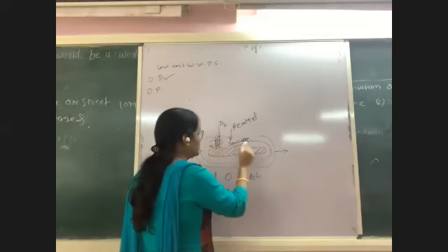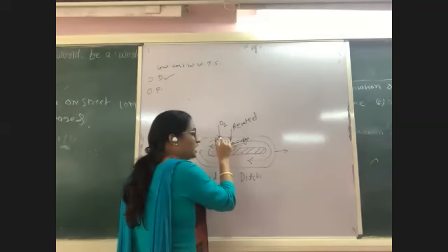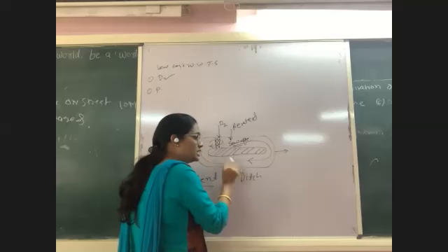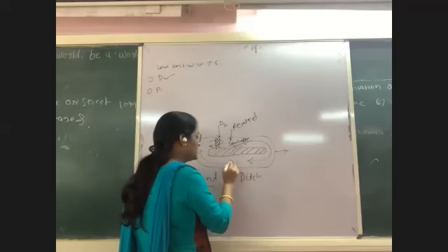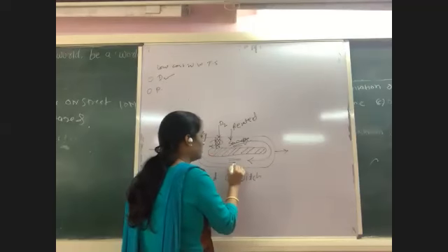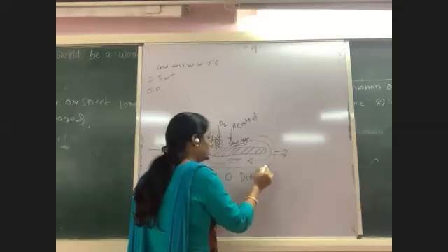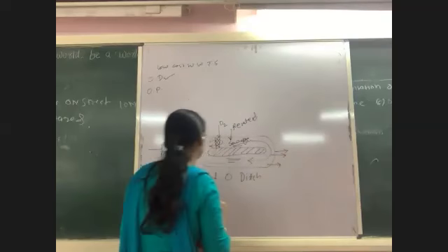Then once the aeration period is over, stop the aerator and allow the sewage to settle in the same tank. So the sludge will settle at the bottom, and the supernatant can be removed from the top surface and the sludge can be removed from the bottom surface.